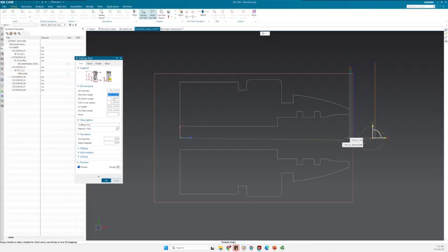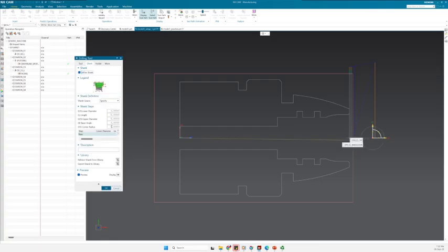Then the rest of these parameters, as you can see, got updated based on the standards that are already recognized. But if they are not correct, it is up to us to define the correct shank. You can see what the geometry of the shanks is. You can easily see what the catalogs of the shanks and tools that you are using are. And it is important that you define it exactly to those ones. If you want to make sure that there wouldn't be any collision or any accident or problematic operation in your operation list, you need to define all those parameters correctly.